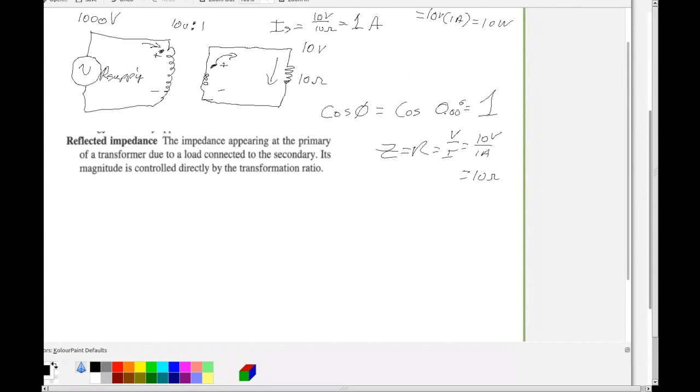All right, so given that, then on the secondary side, remember here, this is our turns ratio. Our turns ratio here is A to 1, which is 100 to 1. Right? So on the primary side, we already said that our voltage is 1000 volts. Okay? Because let's see, 10 times 100 gave me 1000, right?